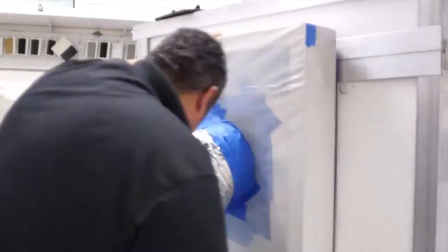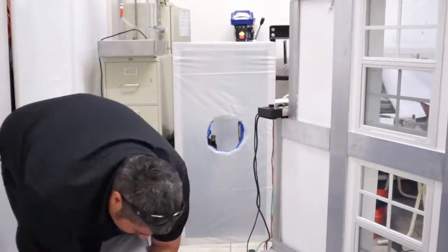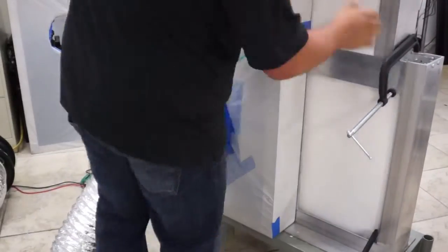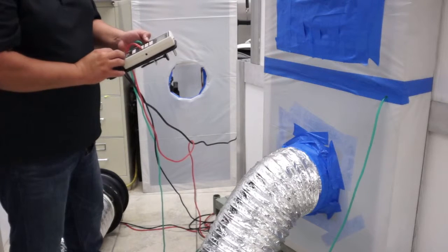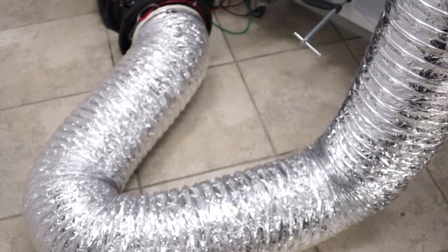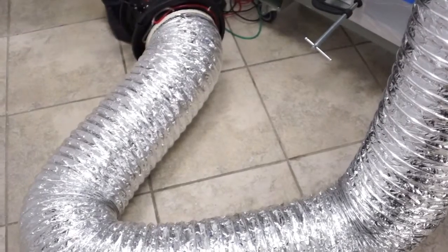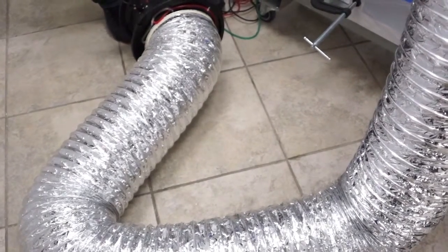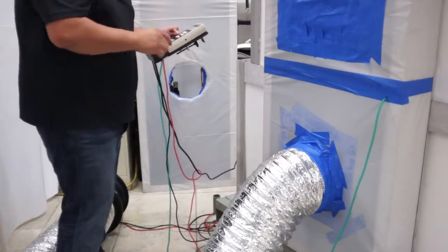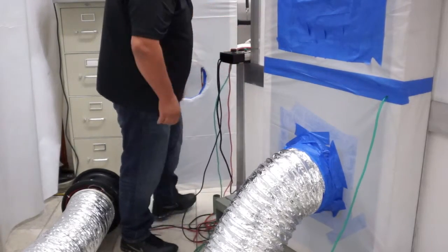Now we will disassemble the chamber and reassemble it to pressurize the lower chamber covering the standard window below. We will set the pressure gauge for the same pressure we used on the upper chamber and turn it on. You can see again the ductwork is expanding as more airflow is passing through. The difference is an extra 300 CFM passing through the bottom window into the interior of the room. This airflow was blocked by the backup window on the first test.